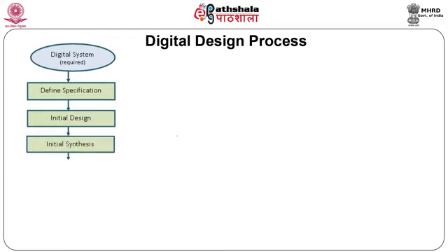The next step in design process is the initial synthesis. Synthesis is the process of converting design entry information of the logic circuit into a set of logic equations. The synthesis CAD tools help the designer to generate logic functions required to implement the logic circuit automatically.